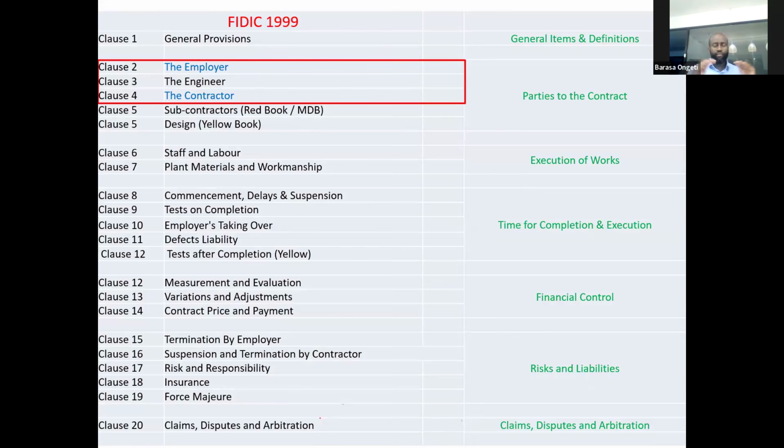So there's no provision for quantity surveyor or measurement engineer under the FIDIC contract. If you're using another contract, perhaps, but if you're using FIDIC contracts, you are the engineer. The quantity surveyor, the measurement engineer, the site inspector, the clerk of works, whatever name or title is given, you are the engineer staff, and authority has been delegated under subclause 3.2.